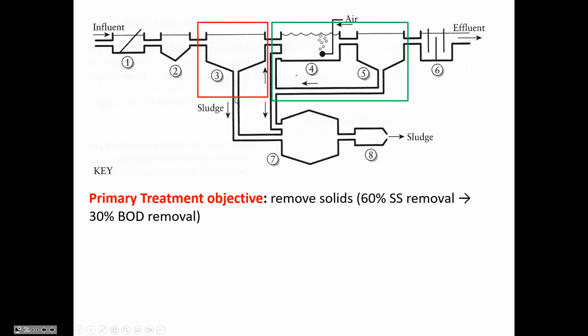And so suspended solids is just referring to that solid fraction of the waste that has to be removed. And some of it is organic and some of it is inorganic. So there's both colloids, which are inorganic minerals like clay particles in wastewater, but then there's also suspended organic material, and we can remove a little bit of both through primary treatment.